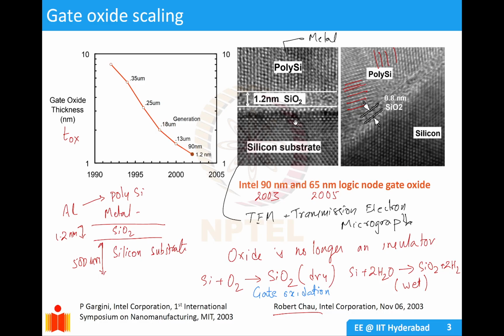This image is taken by TEM, which is transmission electron microscopy. It works by taking a very thin slice of what you want to see and bombarding it with an electron beam. You then read the transmitted electrons and, based on that, make a density graph, and it gives a very high resolution image. You can see individual lattice points in your substrate.